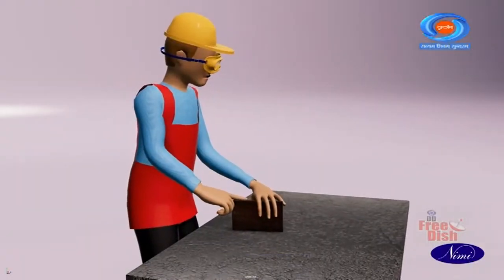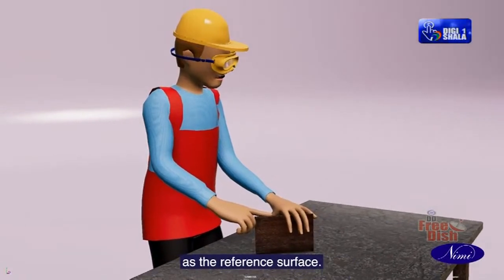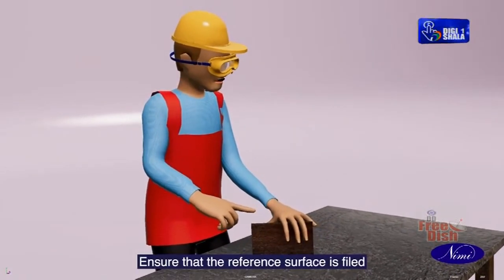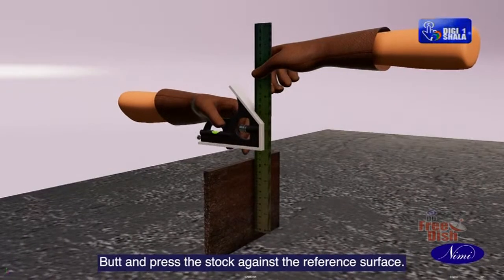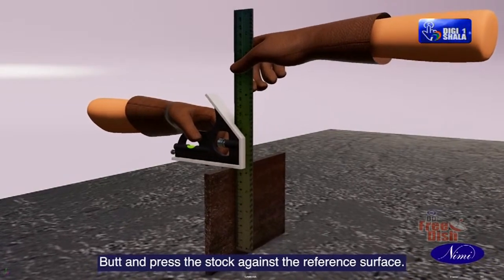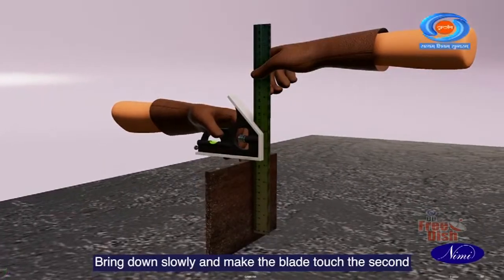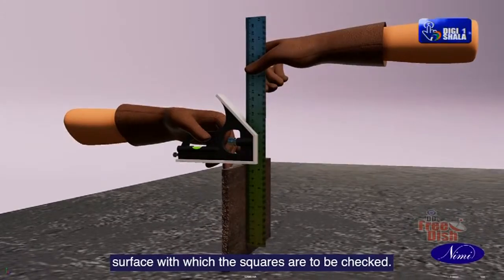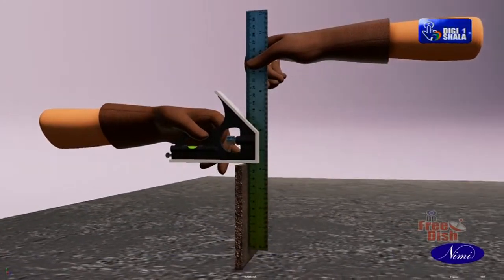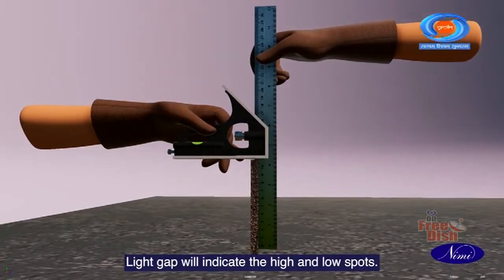Checking squareness. Consider the large finished surface as the reference surface. Ensure that the reference surface is filed perfectly and is free from burrs. Butt and press the stock against the reference surface. Bring down slowly and make the blade touch the second surface with which the squareness is to be checked. Light gap will indicate the high and low spots.